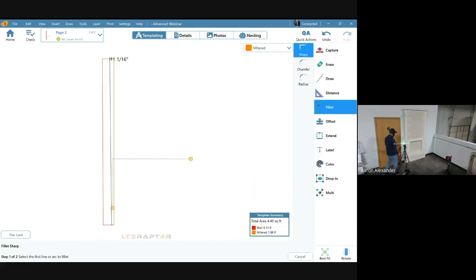So what can I do? I mean, my fireplace is up against the wall here. I'm going to open this door here. And what I can do is get this laser lined up. So again, I am plumb to the face of this thing, hitting right on the corner here. I'll walk you guys over here and show you what I'm talking about. But this laser has this awesome little micro adjust knob on it too, that really allows me to dial the angle in on this thing. It's pretty awesome.